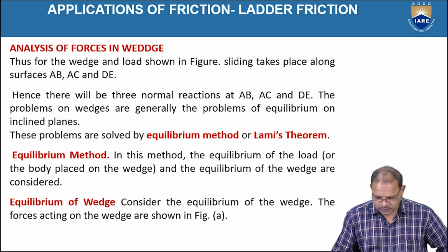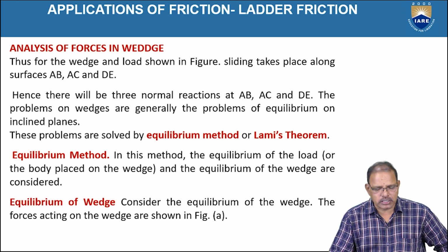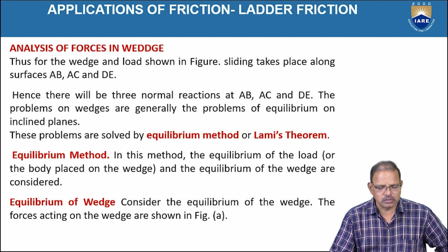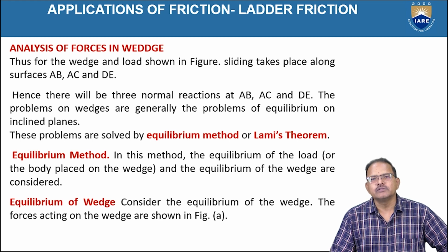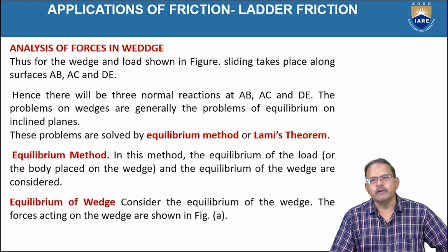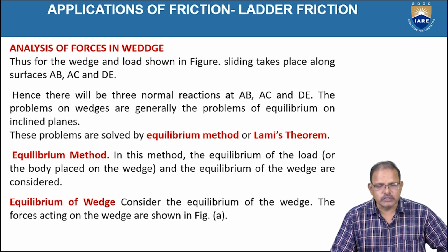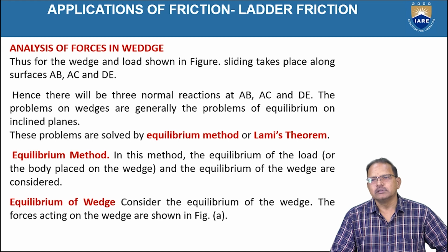Okay, analysis of forces on the wedge. This analysis can be done by using the equilibrium method. In the equilibrium method, the forces are resolved along the wedge, that is the inclined plane, and perpendicular to the wedge surface, as well as at the surface contact.